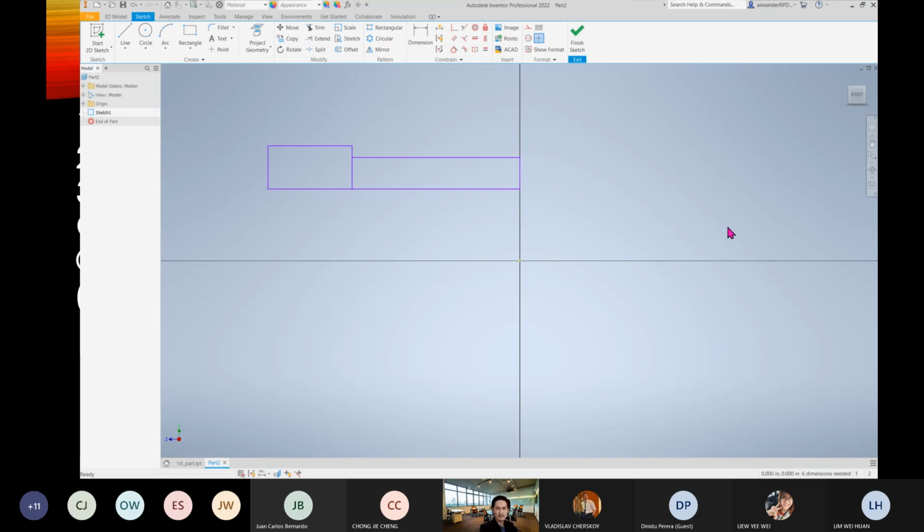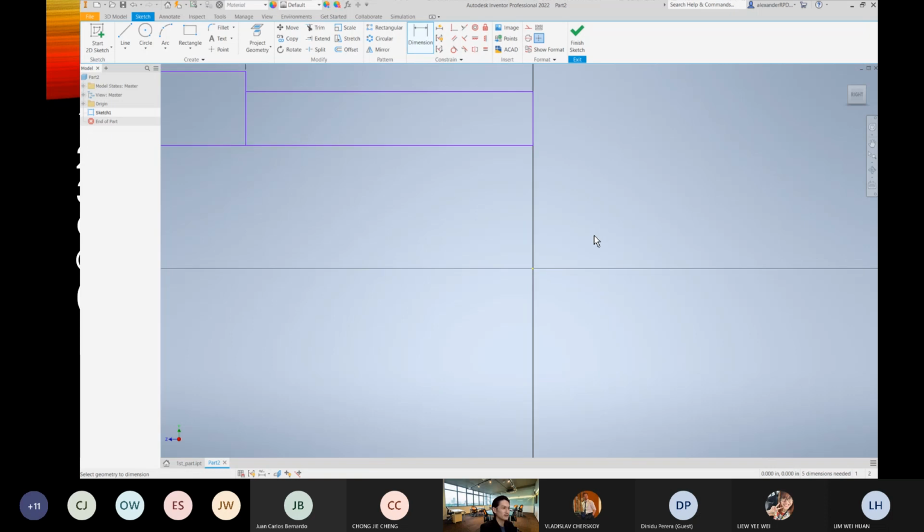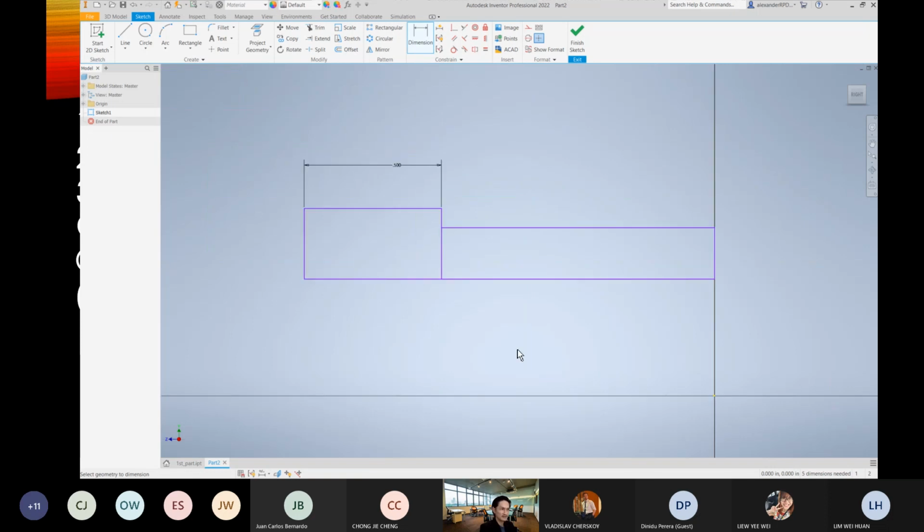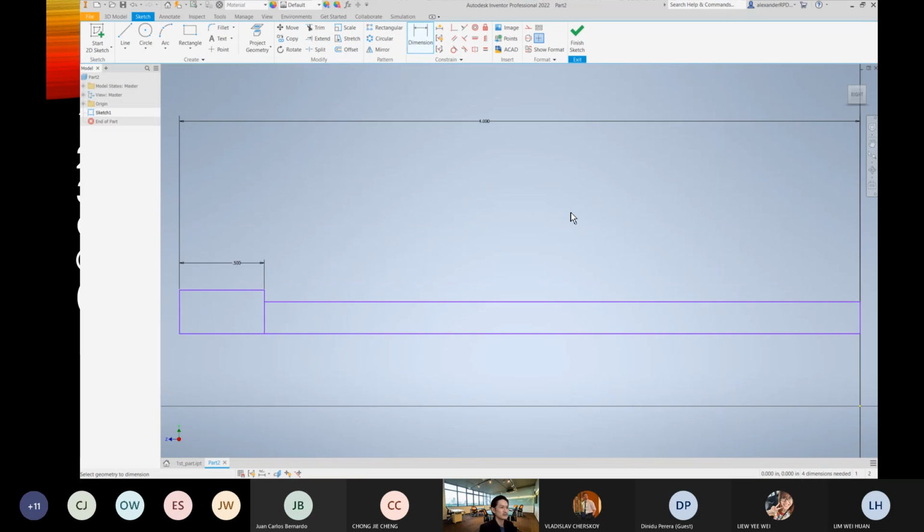Okay, so now I dimension it. You refer together with me. So this one will be 0.5 inch. I already chose inch, so no problem. If you zoom a little bit, it's okay. All we need to do is press the Home button and it gives us the view. The whole length of it is 4, so give 4. Again, the Home button gives me the idea of it.